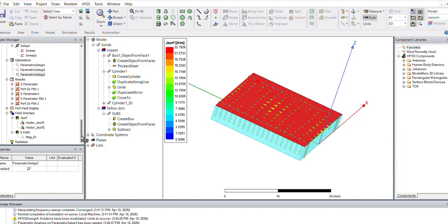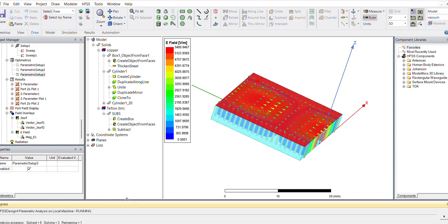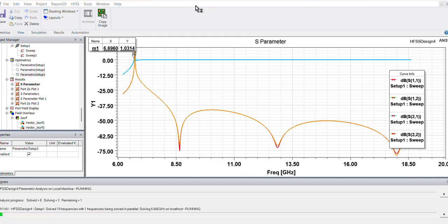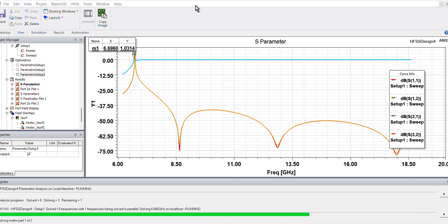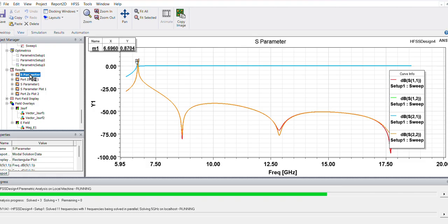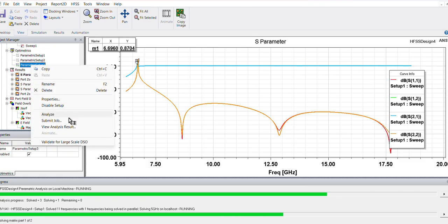And maybe we can also use a lumped port or something like that. If you put in your hole diameters and your pitch length, if you select them correctly, then there will be a seamless transformation. Now we have finished some simulations, and because of the PTHs, the designs are taking much more time to run.